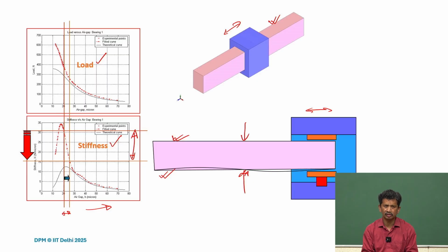That's a big question in fabrication, and getting below 4 to 5 microns is really challenging. Whatever residual tolerances we have are going to change these air gaps. And if there is any air gap change, you see a huge difference in the stiffness, which is not desired. So although air bearings are very good, these are the limitations when we are trying to put them together.